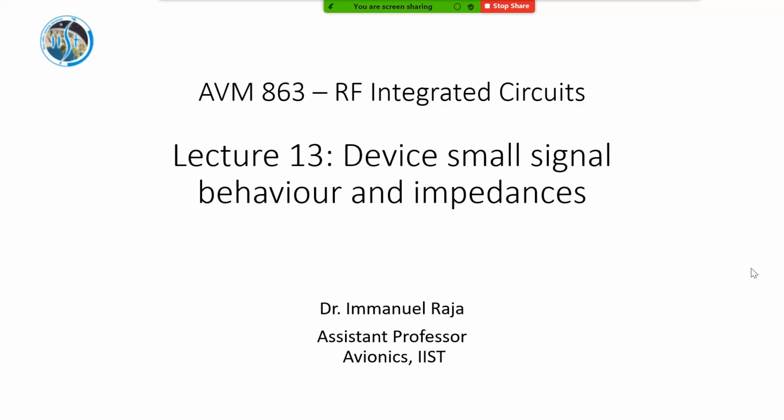In fact, all your Qualcomm SoCs, Samsung SoCs, Huawei SoCs, or even Apple SoCs, the RF transceiver is all in CMOS in your mobile phone. Only the final stage, let's say the power amplifier or some switches, are made in other technology nodes, but otherwise it's all in CMOS.